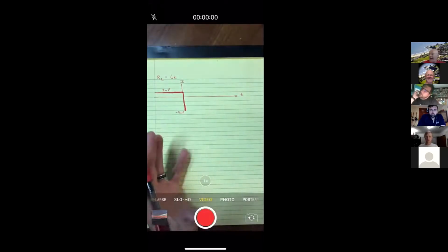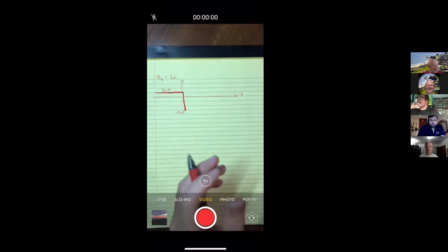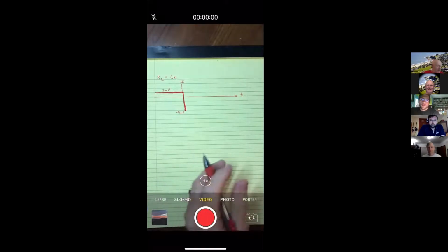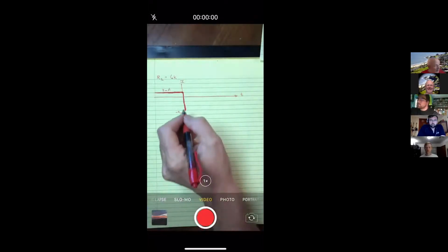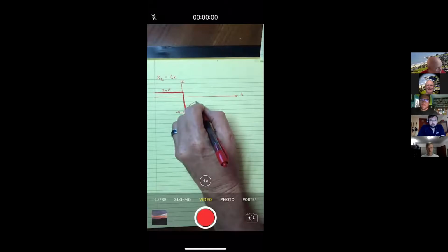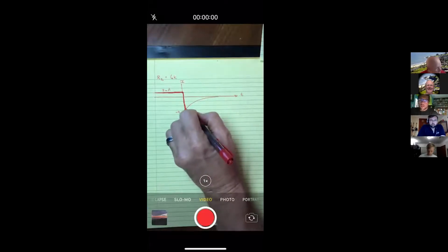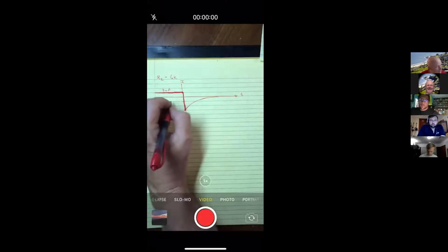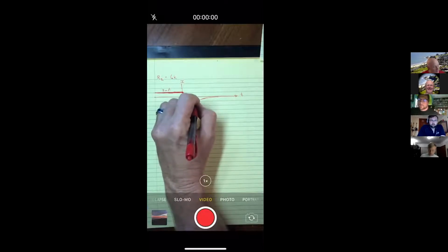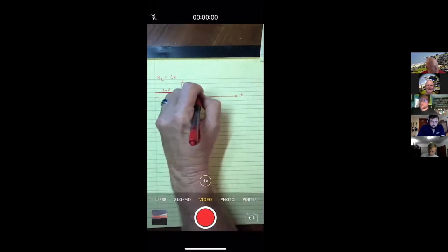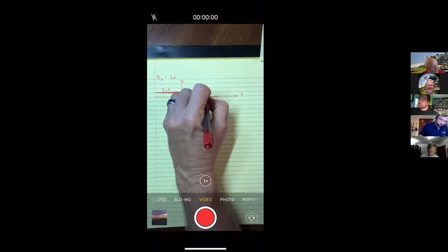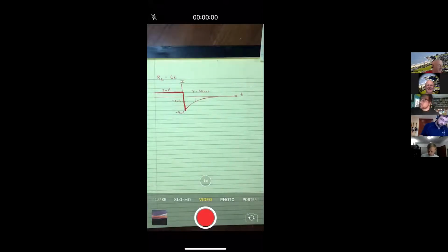All right, now once I get to that, now we're just back to the problem we just actually did. We saw it decaying away. They're in series. It's just we would be defining it as the opposite direction. So it would decay away, and the same thing, it would go down to 1/3 of its value in one time constant, which was roughly 50 microseconds. And so definitely going to decay away.